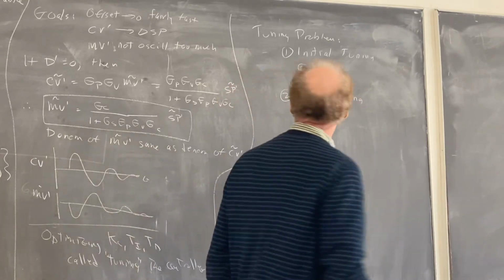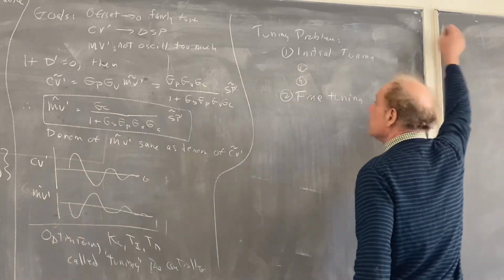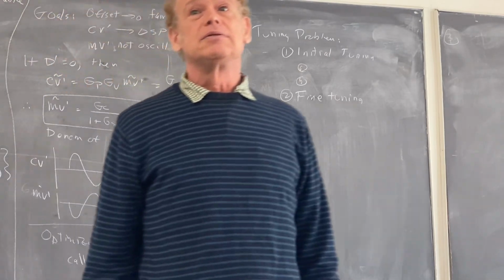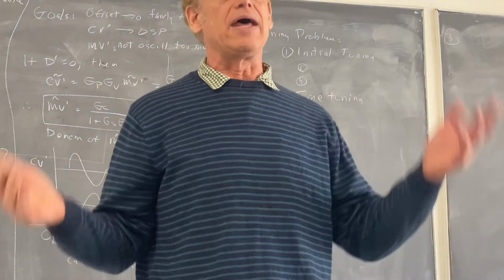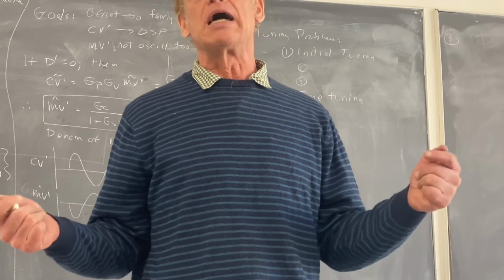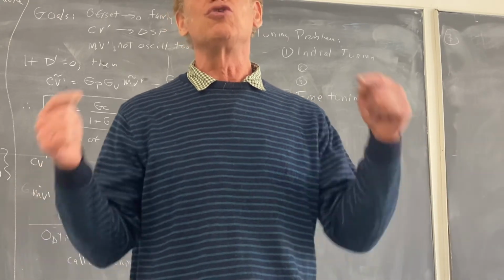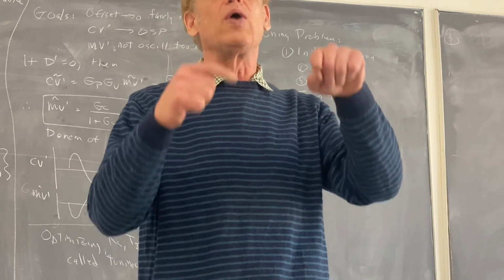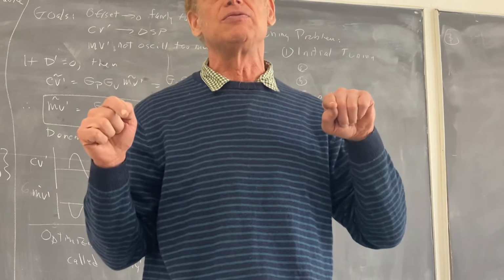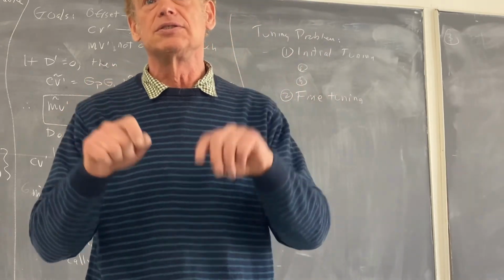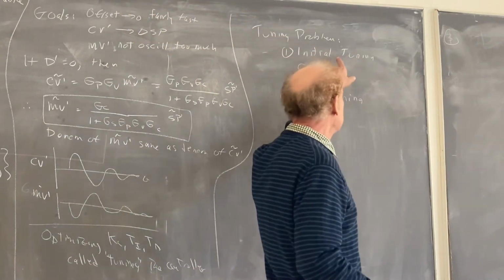So what's the difference? Initial tuning is model-based. As I said, we're going to do the best we can with the model we have. But then we know that the model is not perfect, so we're actually going to go to the true system when we install the controller with the KC, TI, and TD that we've chosen from the initial tuning, and then we're going to do a fine-tuning process. So fine-tuning is on the system, and this is on the model.